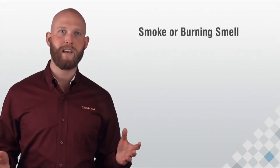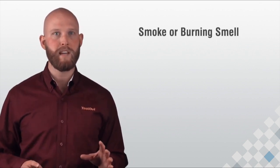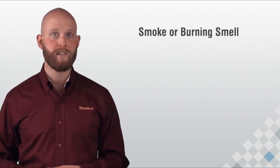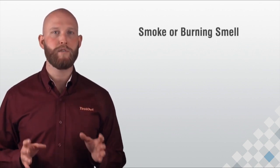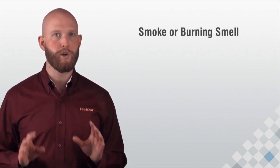Let's end this lesson by discussing what to do in the event of smoke or a burning smell. Both of these symptoms indicate that electricity in the system isn't flowing in the correct paths and it's going somewhere it's not supposed to go. If you see or smell smoke, shut the system off immediately. There's a variety of issues that could cause this issue.